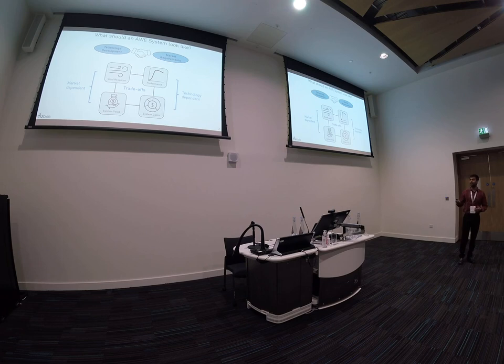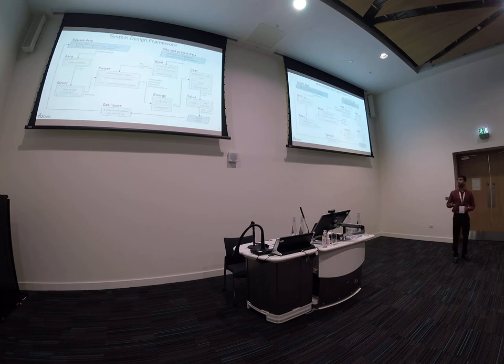Now, how do we integrate all these aspects into a system design framework? This is the overview of the framework that we are building. On the top left, you see the key system design parameters to which all the models in the framework are parametric. That consists of the high-level parameters of the kite, for example, the kite wing area, the aspect ratio, the aerodynamic concept, CL and CD, and for the tether, the maximum tether force and tether diameter. For the ground station, it will be generator-related characteristics.